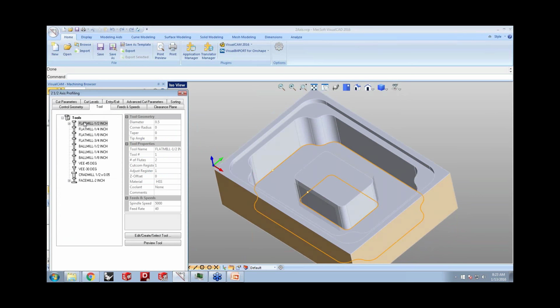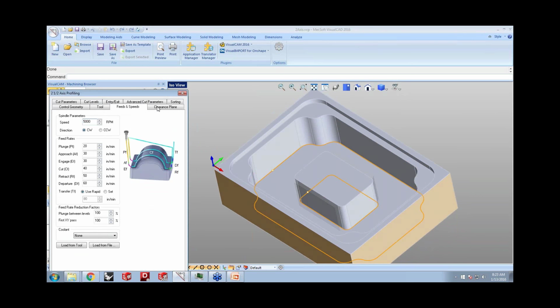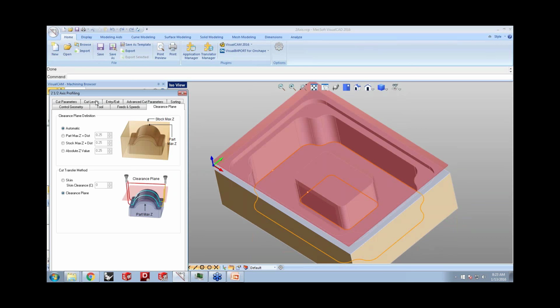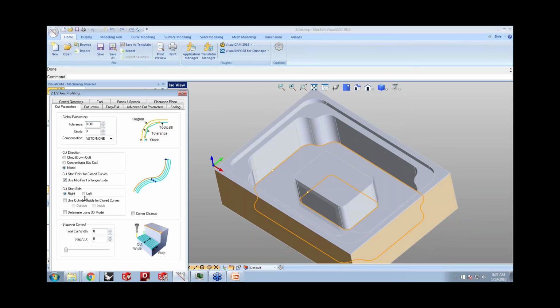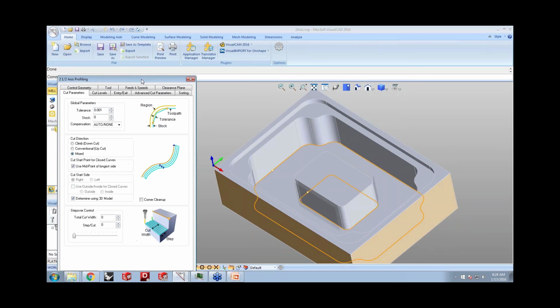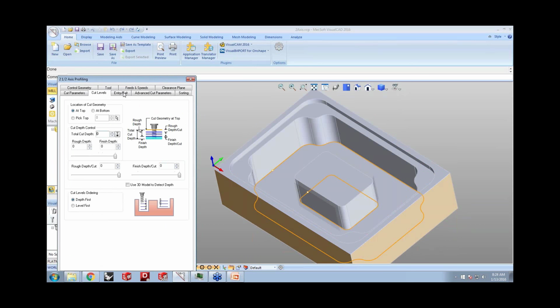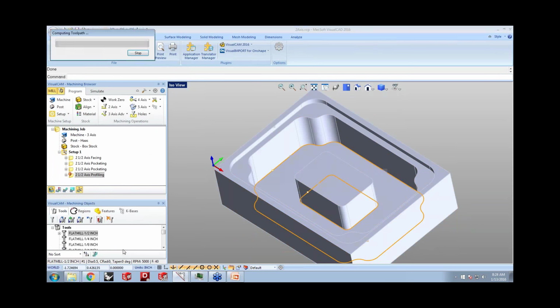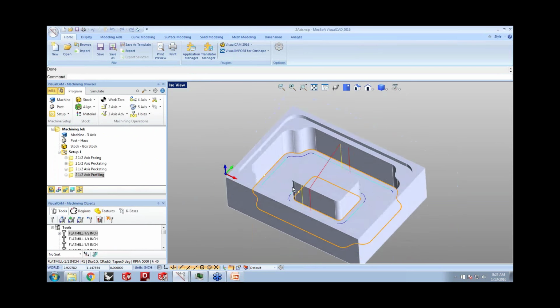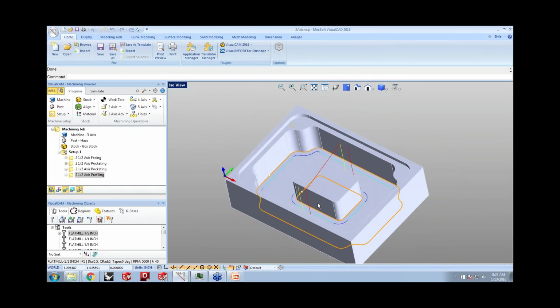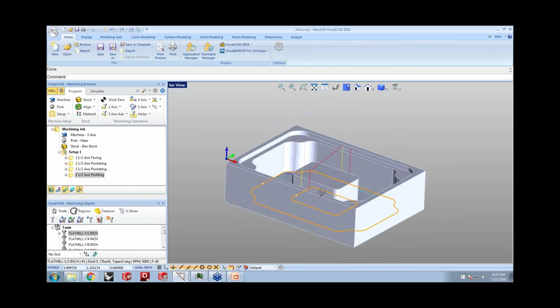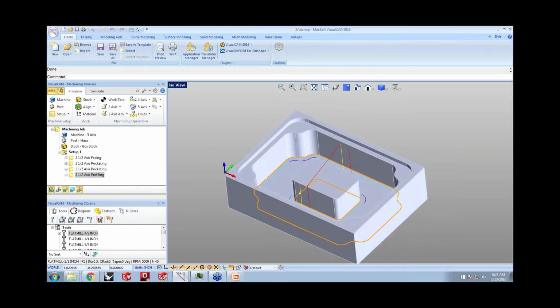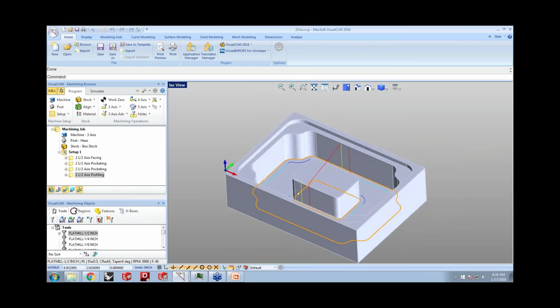We'll grab a 2.5 inch end mill, the same set of parameters for feeds and speeds and clearance. Under the cutting parameters, I'm going to choose Determine using 3D model, so the system will automatically determine which side to place the cutter. Specify my cutting conditions, entry and exit, and then select Generate to create a toolpath. And there it is. So this basically gives you an overview of the 2.5-axis methods that are offered in Visual Mill's module from standard through Pro and Premium configurations.